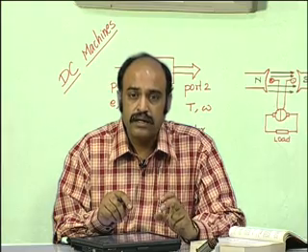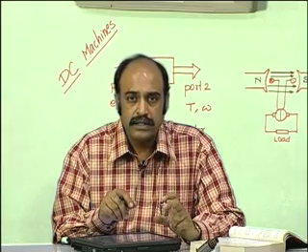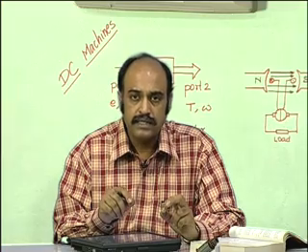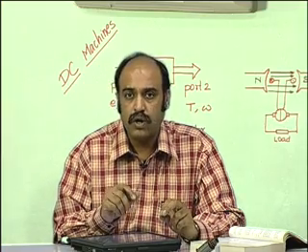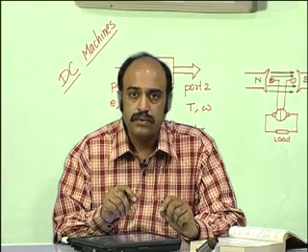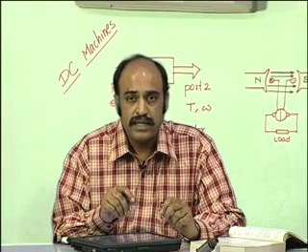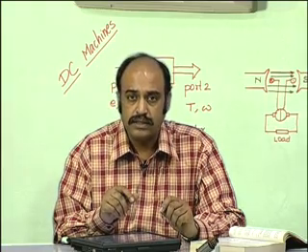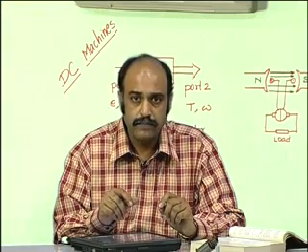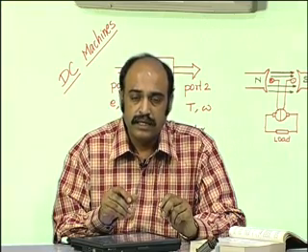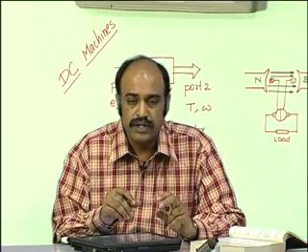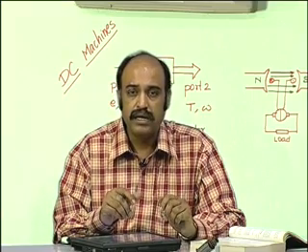And the second, a more important thing, is that the voltage across the brush will have much less ripple as the number of coils and slots increases. So, these two are the primary advantages of having a large number of coils. Further, if the number of poles is also increased, then the ripple content in the output of the DC machine will be negligibly small.